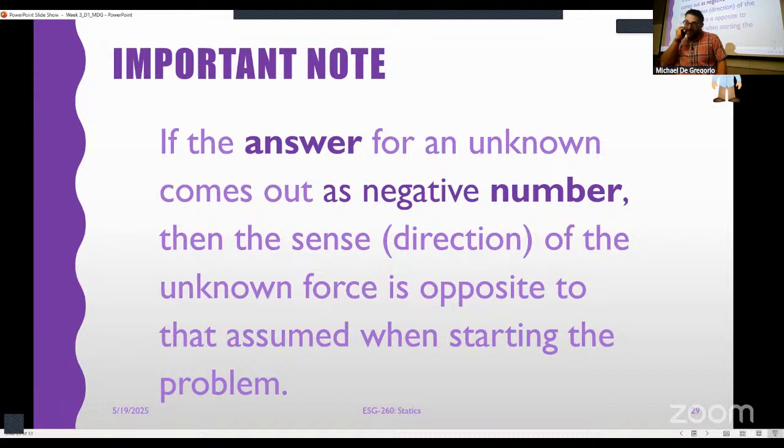We talked about this a lot. I say this like every time. But remember that when you use these equations, they are scalar equations, and so if it comes out negative, that is just telling you that you have to draw it in the other direction. So keep track of it. You will start seeing me write down this goes to the left, this goes to the right. Instead of me redrawing the whole free body diagram at the end, I just keep track of it with my answer. And that's fine. You can also redraw the free body diagram if you really want to. That's up to you.